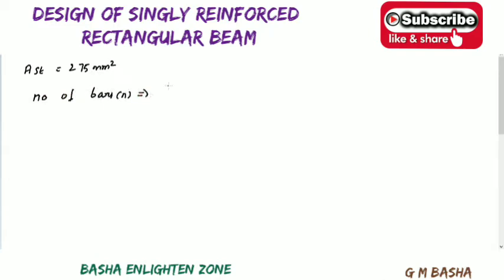So the formula will be capital Ast by small ast. Here capital Ast means whatever the area of the steel obtained here, that is 275, and small ast will be pi dia square by 4.